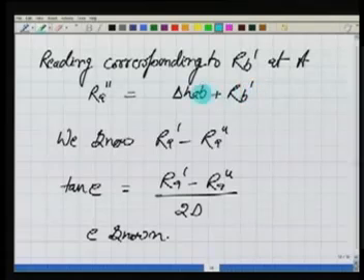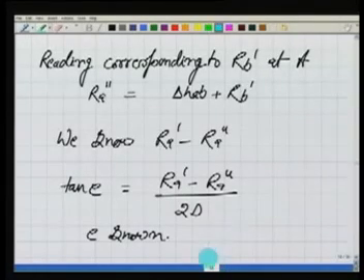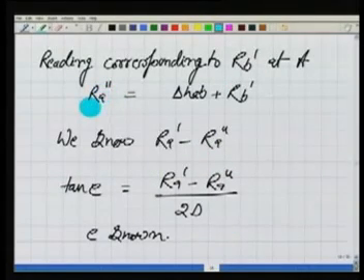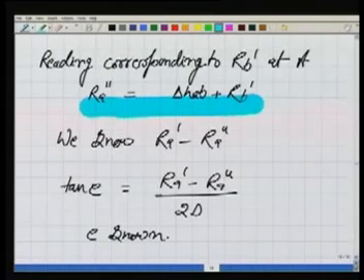What is the meaning of that? The meaning is, had there been no error, and if my instrument is bisecting the staff at B at RB dash, where should it have bisected the staff at A? It should have bisected the staff at A at point RA double dash, because the line of sight should have been horizontal. And if it is so, I can find this value.